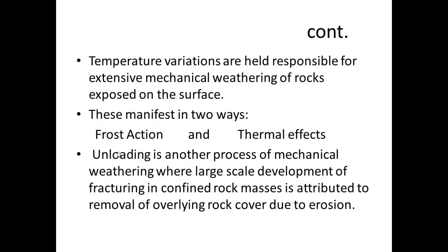Consequently, joints develop in them parallel to the uncovered surface, dividing them into sheets. This rupturing or jointing in itself is a mechanical breakdown of the rocks. When these ruptures take place, this is the mechanical disintegration or breakdown of the rocks, and makes them available for further weathering along the joint planes. This whole phenomenon is known as unloading.